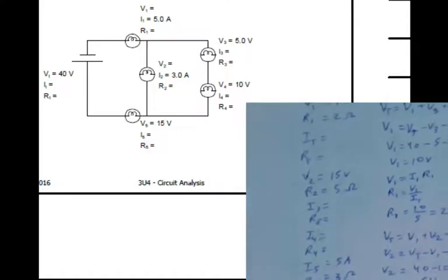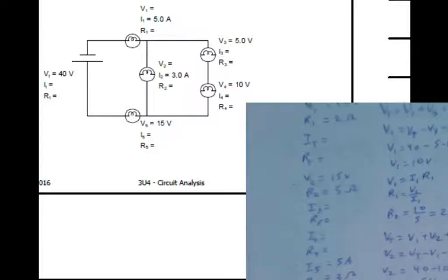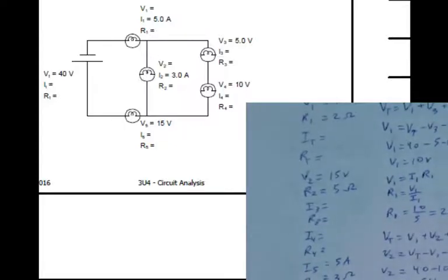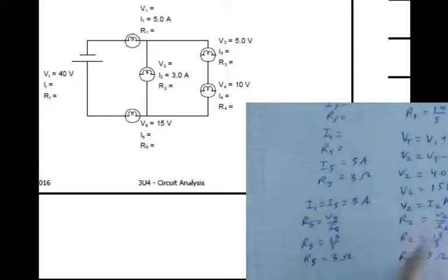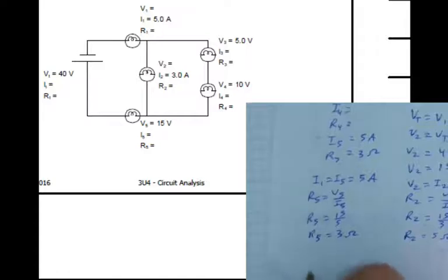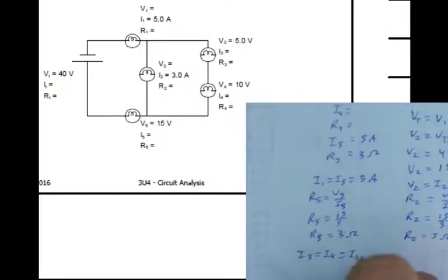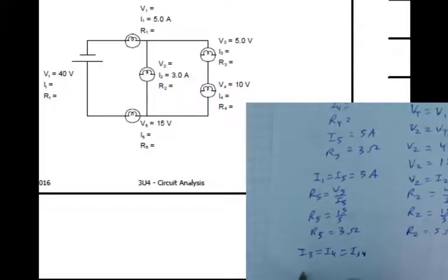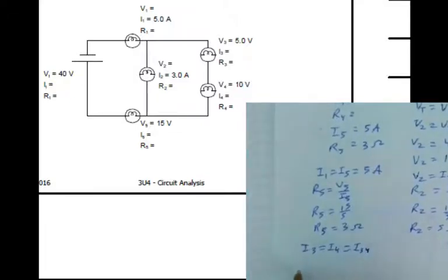So I need to now analyze 3, 4, and the total. Well, if I know 5 amps is going into that junction, then at that junction, let's say I3 equals I4, and let's just call it I34, because it's the same. At the junction where we split into I2 and I34, we are going to have I1 equaling I2 plus I34.